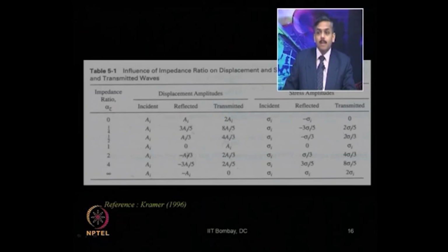But where does the big difficulty arise? Difficulty arises with respect to this displacement. That is the reason an earthquake wave which is not imperceptible or not that damaging at large depth in rock media, when it reaches through various soft soil, there will be a manifold increase of the displacement amplitude of that wave.